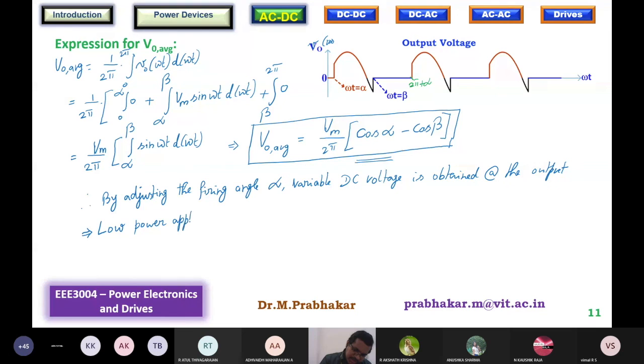It could be heating application, like heating. Don't think of heating and smelting in terms of megawatts. No. They need full wave rectifiers, fully controlled full wave rectifiers. Fully controlled itself means full wave. I know that, but you should know that. So very small heaters, power rating till 100 watt, 200 watts, there you can use this, because even if 1/2 cycle is not going to be available, the heat is not going to come down drastically because of the inertia. So for very low power applications, half wave controlled rectifier can be used. That's all.